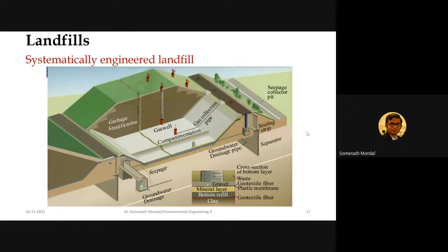So you have additional facilities to recirculate the leachate which is getting generated, thereby enhancing the decomposition rate. So these are the different ways you can increase the efficacy. And we have a certain time period for constructing the landfill, for dumping into the landfill, and then keeping it for the entire decomposition.